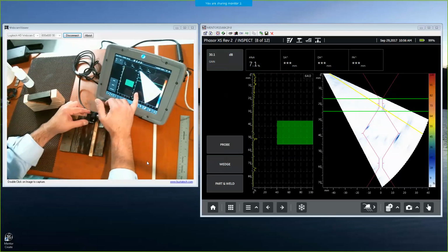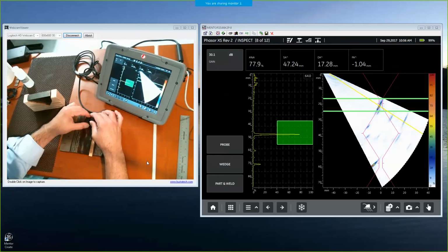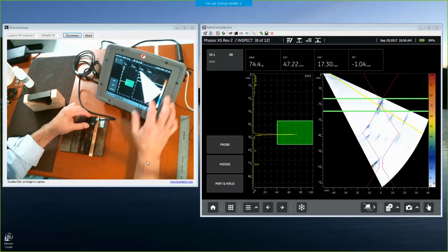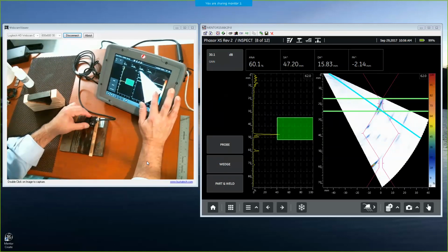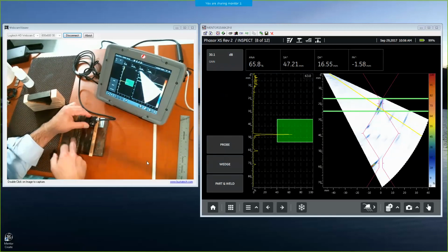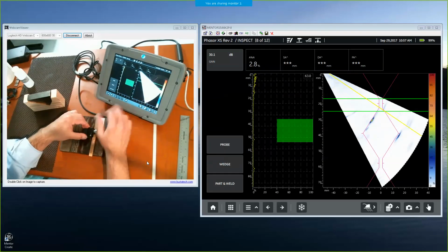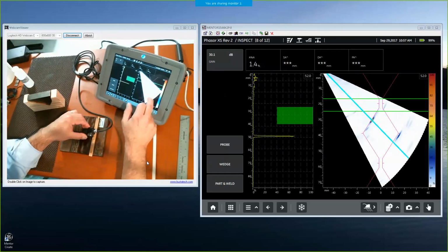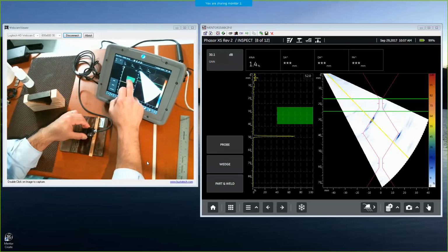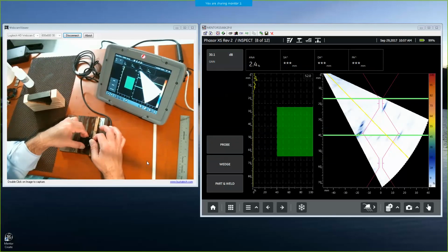So I've got a sector and an A scan. So scan along. Oh, there's something interesting. I've already got the selected beam up there, but yeah, I can select our beam. So we have our A scan, and that's the lack of fusion down at the bottom. If I scan along here a little more, oh, there's the next indication. Bring my beam selector down. There's that bit of slag or inclusion. Come on out here. There's my surface breaking crack.